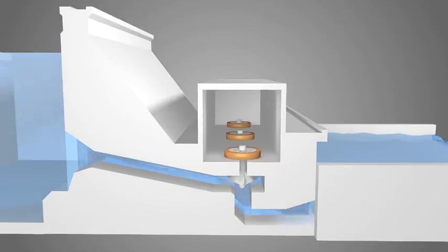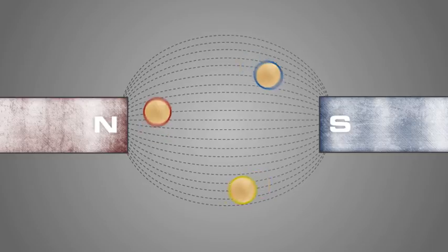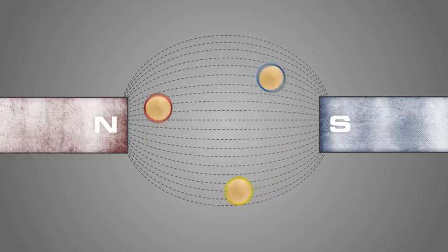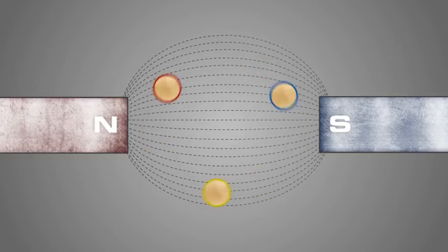The electron flow is sent to power station transformers that increase, or step up, voltage from the power plant to higher voltage transmission line levels for long-distance transmission of power. Alternating current is normally preferred, as its voltage may be easily stepped up by a transformer. This minimizes resistive loss in the conductors that are used to transmit power over great distances.